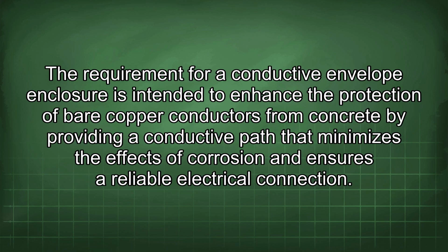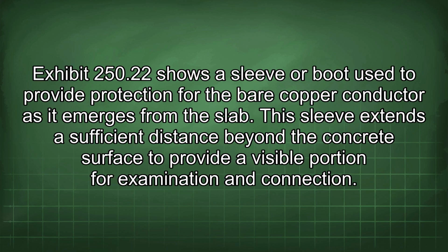The requirement for a conductive envelope enclosure is intended to enhance the protection of bare copper conductors from concrete by providing a conductive path that minimizes the effects of corrosion and ensures a reliable electrical connection. Exhibit 250.22 shows a sleeve or boot used to provide protection for the bare copper conductor as it emerges from the slab. This sleeve extends a sufficient distance beyond the concrete surface to provide a visible portion for examination and